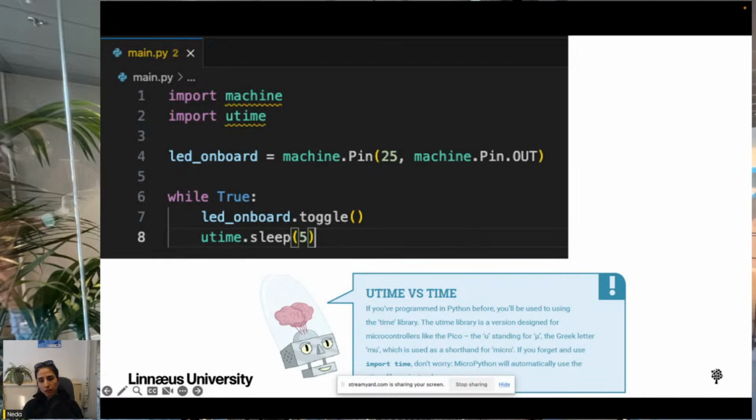The reason is that on full computers that run operating systems like Linux, Windows, or macOS, programs usually run, do their job, and then terminate and return control to the operating system. In this way, many programs are run all under the control of the operating system. And the operating system is the only program that runs from power on to power off. On microcontrollers, typically there is no operating system, and the only thing that runs is our program.